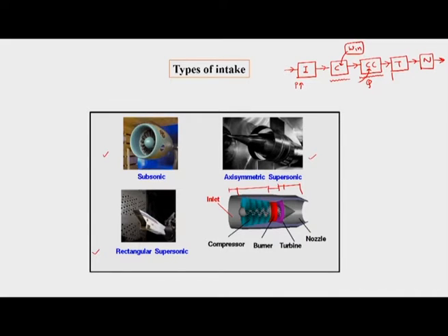And then in the case of intake, we would practically have the intake as a diffuser, since we know a diffuser is a duct where pressure is increased and velocity is decreased. This is what we have seen in the case of incompressible flows also, where we can apply Bernoulli's equation, and we can see that in a diffuser we will have a pressure rise and velocity decreasing.